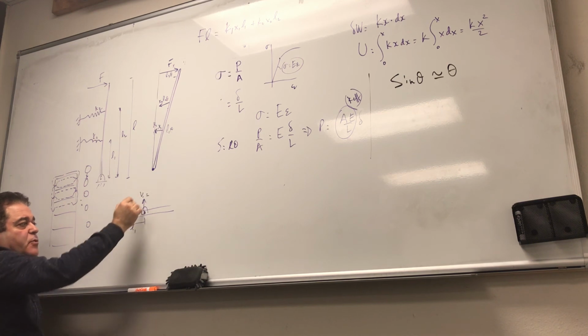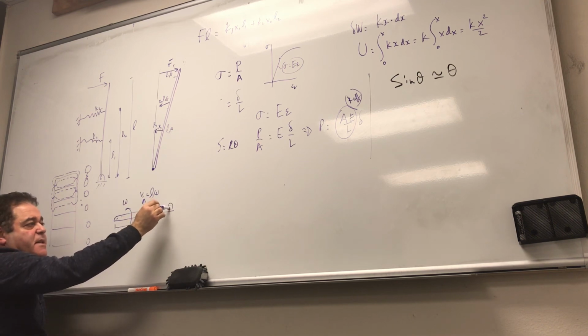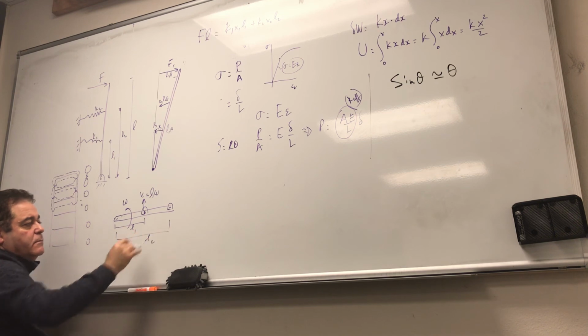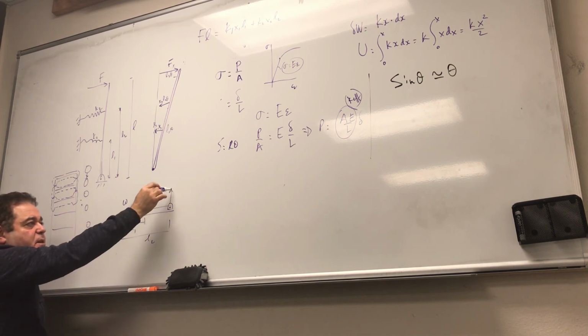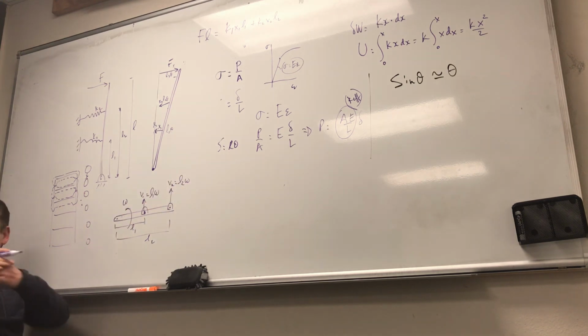Well, V1 is going to be equal to R, which is L1 omega. How about if I have another mass that's in here at a distance L2? The velocity of this one will be V2 equals L2 omega. Remember, the farther you are from the center of rotation, the faster you're going, right?